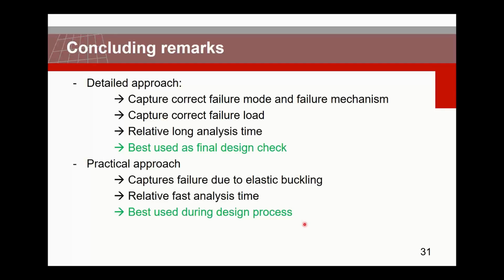Just to conclude. So the detailed approach, if you would want to use that, we can capture the correct failure mechanism and the correct failure mode. Also the correct failure load, so that means at which layer it will fail. The only thing is, of course, the analysis time is relatively long. So it's best used basically as a final check.